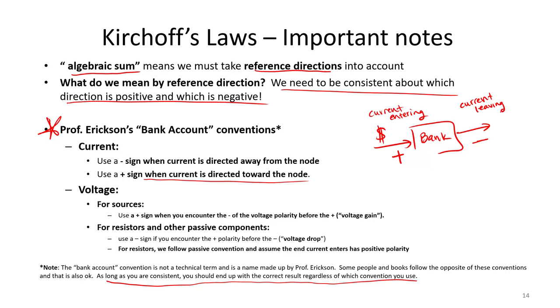We use a similar type of convention for voltage sources. For sources, I like to use a positive sign if I encounter the minus end of the voltage source before the plus. Because essentially what I'm doing here is I am gaining voltage.